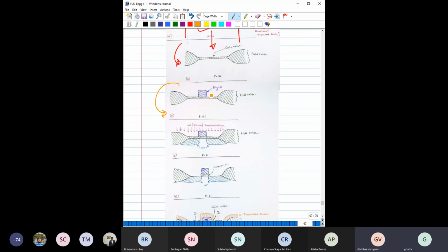All right. Okay. Then after that, what we have done on this, so we have already this gate oxide. So on top of it, I have placed one polysilicon gate. So here you can see that metal is not possible. I have not used metal. I have used rather polysilicon as a gate. There is a reason why polysilicon is required, why we cannot use metal. I will just come to it, but first see the total process step.